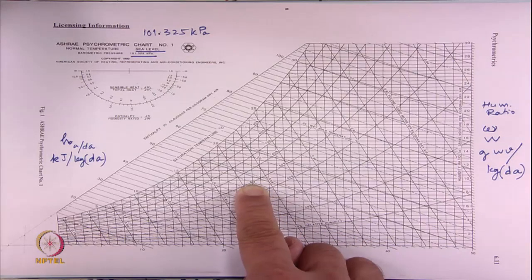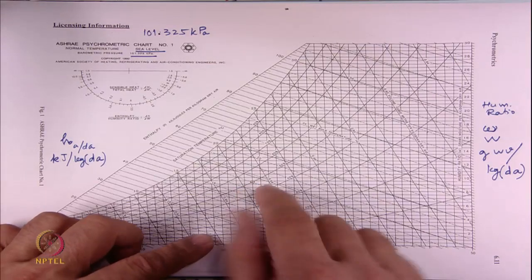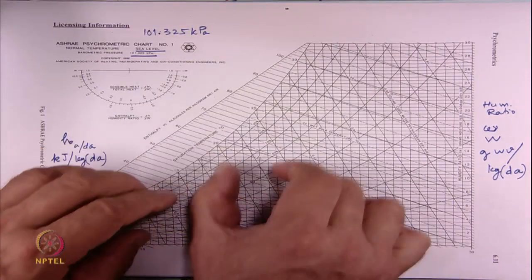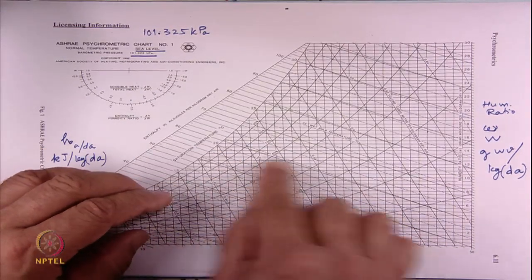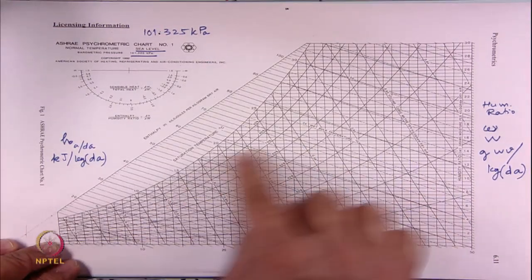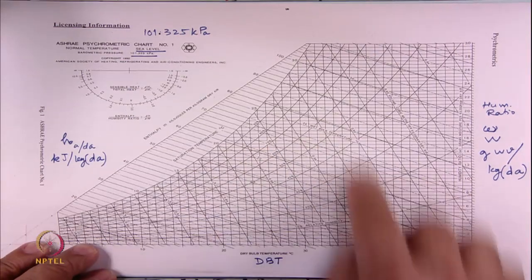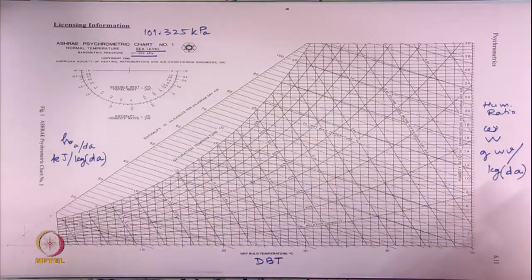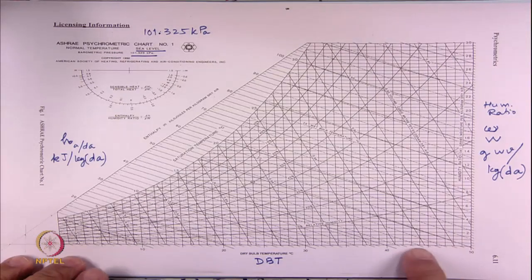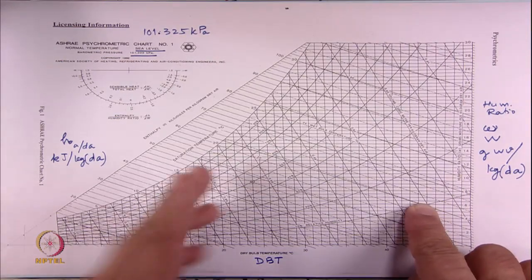Everybody thinks that if we have this, that is the most comfortable condition for all of us, but then there is always a range. We say that it should be between these humidities and these WBTs. So, we end up making a region here which says that this is the most comfortable condition. Then you go slightly away from it, a little less comfortable. You go further out, more uncomfortable, and then it goes on like that. And we are all quite familiar with this: when we have 45 degrees Celsius temperature and very low humidity, we are sitting somewhere here, way out of the comfort zone.